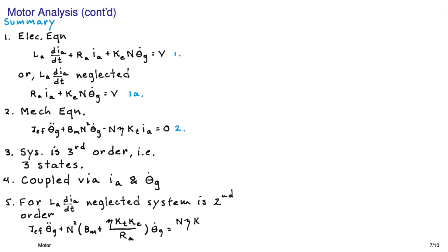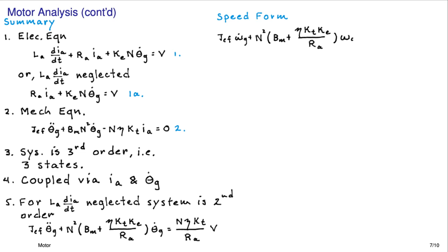Now here we can see some of the effect of the back EMF. It presents itself as a damping term. So that's really important just to get a physical sense of what the back EMF does to the mechanical side of the dynamic system.